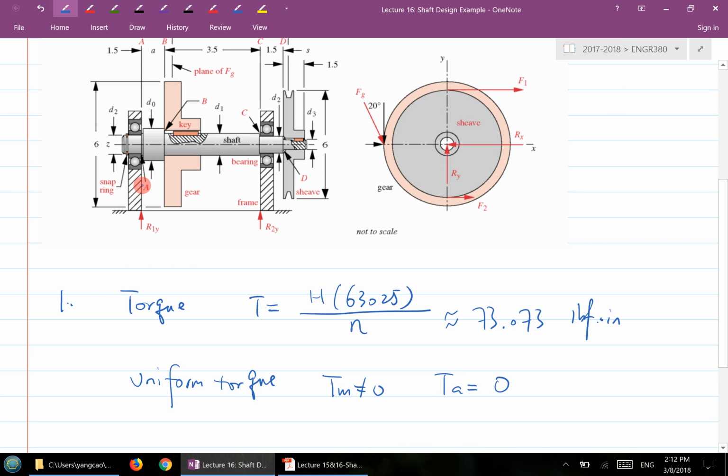By looking at this question here, it made an assumption which I would recommend that you actually don't use. Basically, it's assuming the width of the bearing to be very narrow. So the supporting forces at the bearing location are simplified to the edge of the bearing. Okay, so the two supporting forces, see that? It's simplified to the edge of the bearing. But when you do the shaft design, I would recommend that you use the center of the bearing for more accuracy. But anyways, for this one, let's just consider using this example.